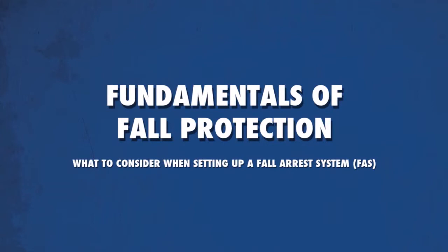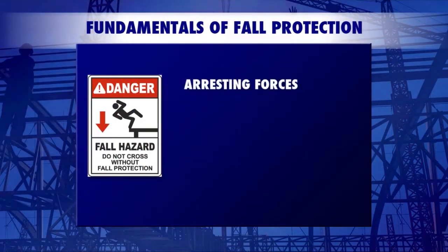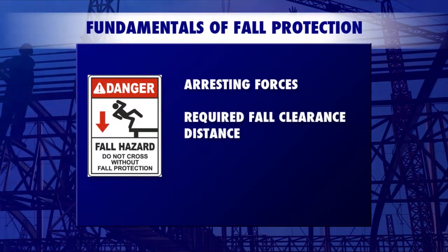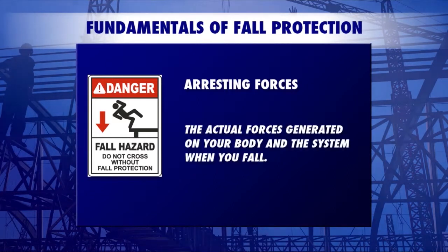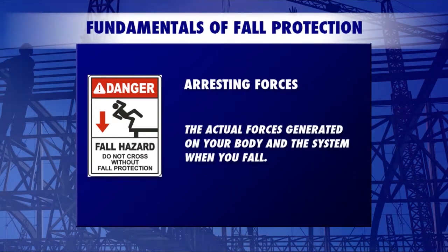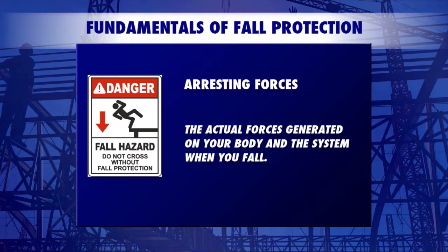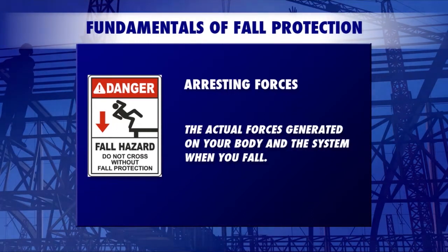So now that we know about the ABCDs of fall protection, we can talk about the fundamentals of fall protection and what you need to consider when setting up a fall arrest system. These include arresting forces, required fall clearance distance, and swing fall. Let's begin by taking a closer look at arresting forces, the actual forces generated on your body and the system when you fall.